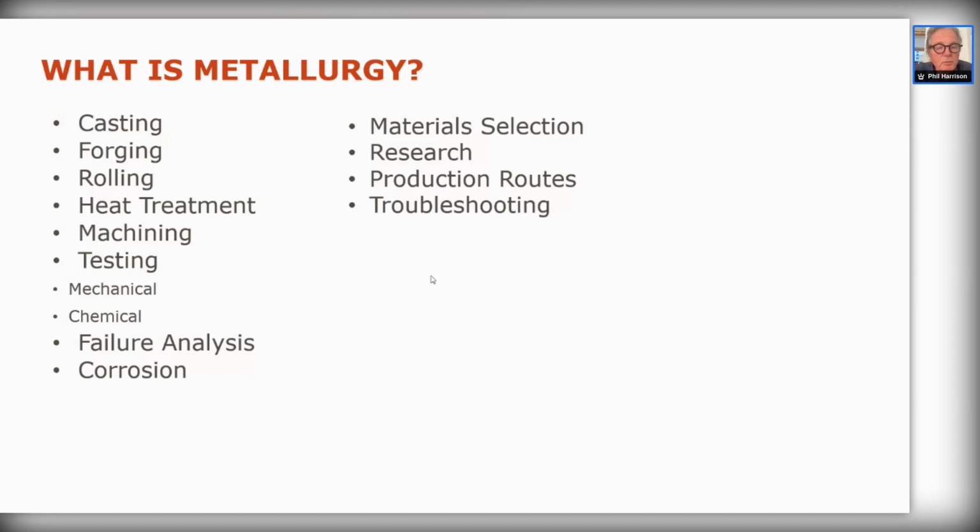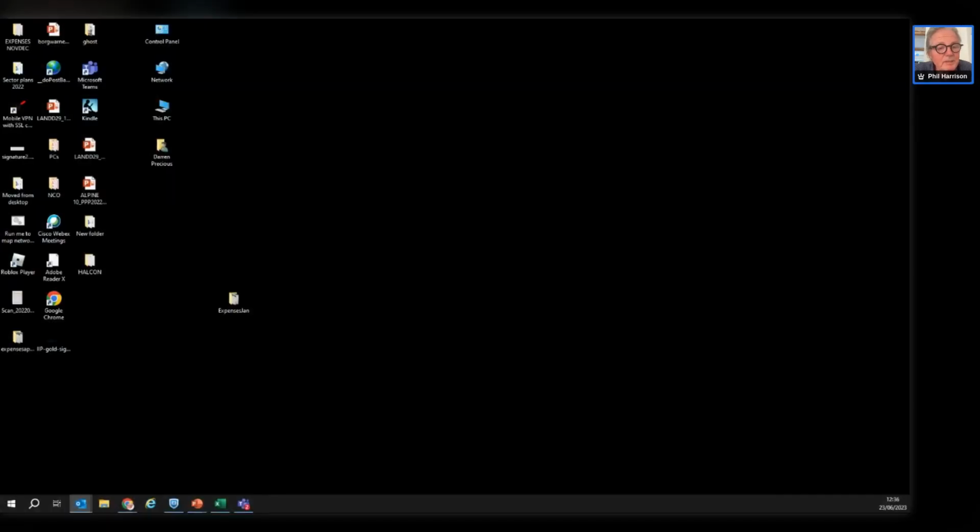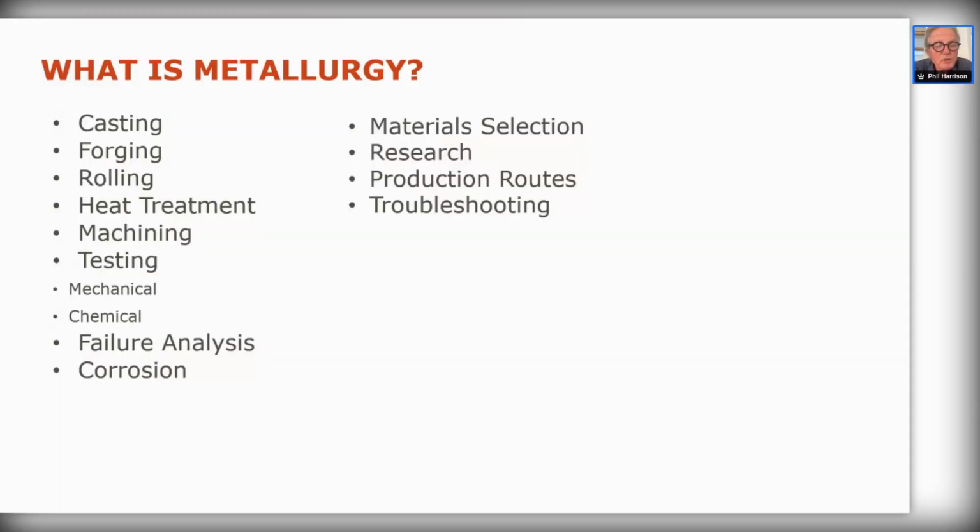The heat treating can take various different routes. We can use steel, where we do what's called a quench and a temper. It might be surface hardening, where we're using something like carburization of a steel. It might be a solution treating and age process that we do in aluminium alloys, or it might just be a straightforward annealing, where we're removing any built-up stresses in the material. And these stresses can result in problems at a later stage. For example, the stresses can affect fatigue life of materials, can affect corrosion of materials.